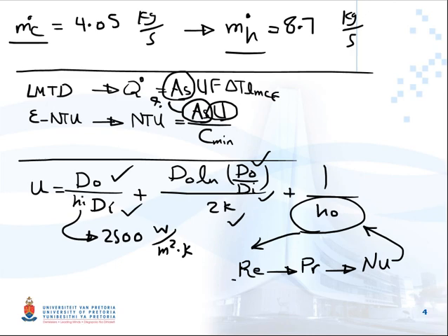So we did the same procedure. We calculated Reynolds to be 1211. We also said, from the information that we had for the thermophysical properties of the hot fluid, which was ethylene glycol, that Prandtl is equal to 26.12.